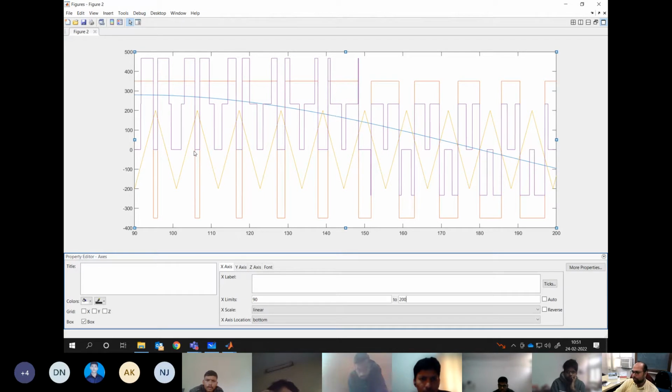You understand my point? So basically more voltage is required for realization of this average value. That's why it is coming like that. Here during this, only VDC by 3 and 0 are sufficient. Sometimes it may have a small notch which is like going for 2 VDC by 3. We can ignore that sometimes. It's a very fine notch.